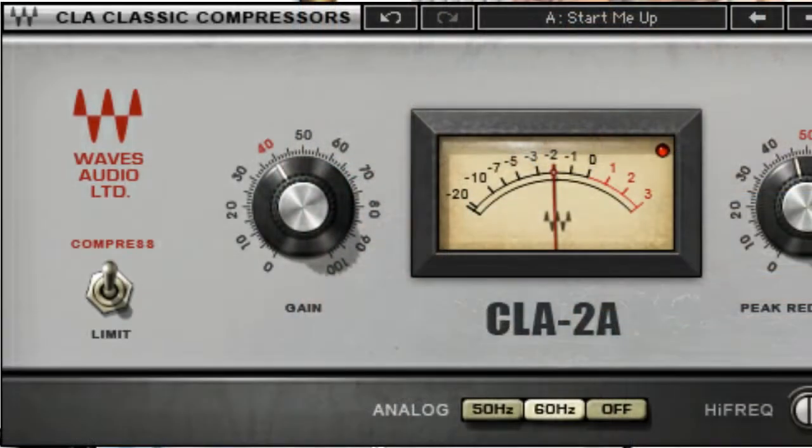Correctly, a compressor is designed to reduce dynamic range. It will increase the general volume level and decrease the loud passages. A limiter is designed to prevent the output of an audio amplifier from exceeding a predetermined level. It should not affect the sound in any other way. In the real world, the definitions of compression and limiting become confused. Compressors are often used to control output levels, while limiters are often used as compressors.